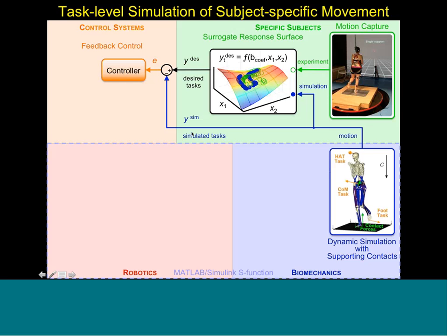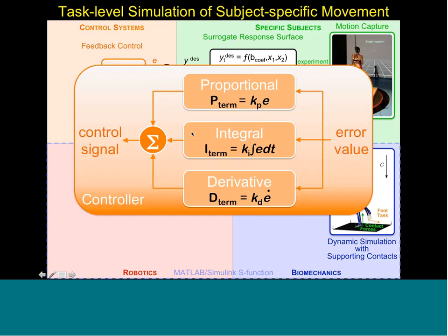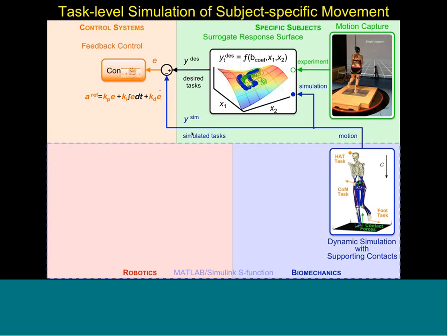In addition, because we are simulating humans here, looking back to the literature, there's a time delay. It's about a 60 millisecond delay that we added. The output of the controller is the delayed reference task acceleration. So we get some kind of acceleration output from these controllers, but it's all delayed to represent the human neuromechanical process delay.